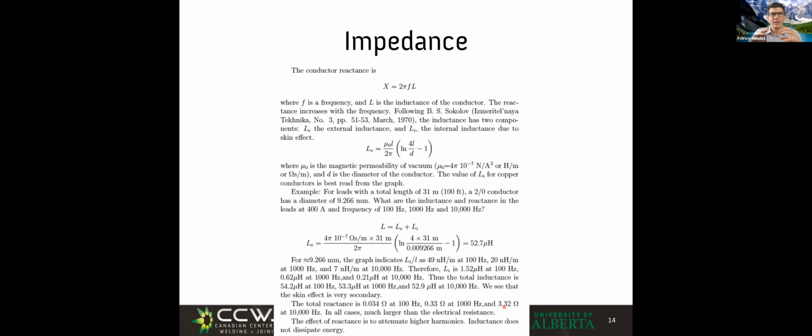You can decompose any pulse into a series of pulses that involve many frequencies. The sharp edges are associated with the high frequencies. What this means is that if I have long leads that have a high impedance, I'm going to be filtering the high frequencies that give us sharp edges in our pulses, and I'm going to have a dull pulse.